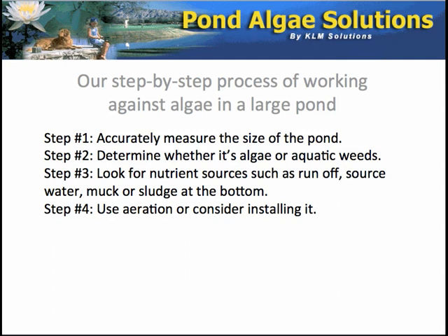Aeration alone may not turn an algae problem around, but it's a precursor to doing it in the most effective way, and there are cases where it alone can improve the condition so much that algae will begin to clear up. So making sure that you have a subsurface aeration system, that's one that's going to release air on the bottom, is probably the best way to go, and these are usually sized based on the depth and the area that you're trying to cover.